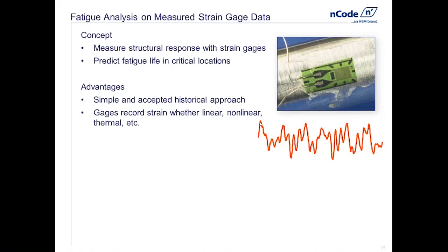And that can be a good thing because we can sometimes oversimplify loading scenarios in our head and then collect measured data and find actual loading is maybe not quite so simple, and we can learn then about characteristics of customer usage and so on. The downside to this is that we need a strain gauge in each hotspot, so this can be a bit laborious at times if we're working with, say, a large structure that needs 100 or more strain gauges to understand all the different hotspots.